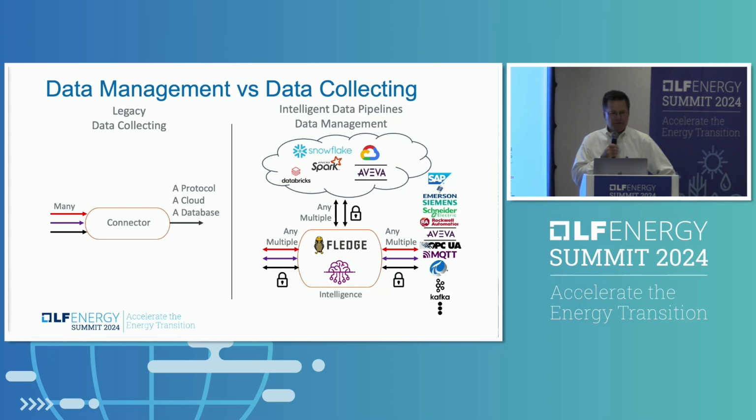So what you end up with is a database that has all the data, of course. Then there are these new ideas that new protocols solve everything, whether it's MQTT, Sparkplug, or OPC UA. So I'll take all these different protocols, connect them to OPC UA, and I'm done. This doesn't work. What you really need in an intelligent edge is the ability to collect from any machine, any protocol, any data map, and integrate that with one or multiple destinations of any protocol. I can send it to the cloud, the historian, the MES system, the maintenance system, and I can format the data with the schema necessary for the group consuming it.